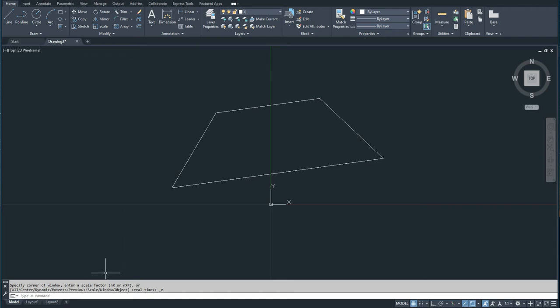It could be by mouse or by writing words here, and AutoCAD will display its message to you in the command window. So keep your eyes on the command window, so you can read the current question or the current option, and you can respond to the commands or options.